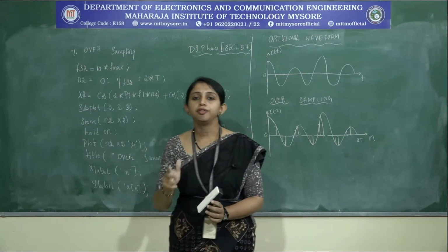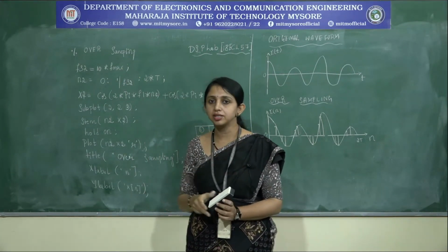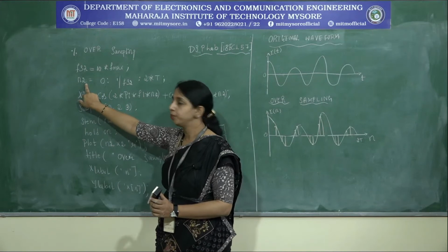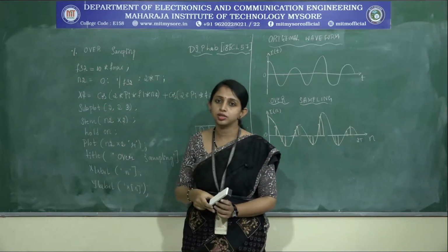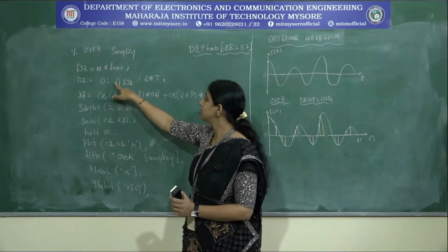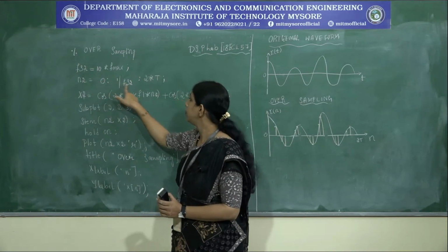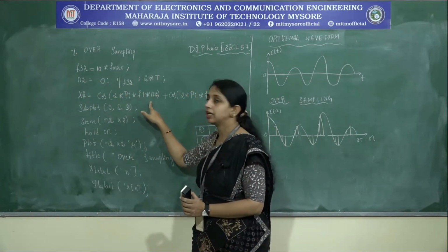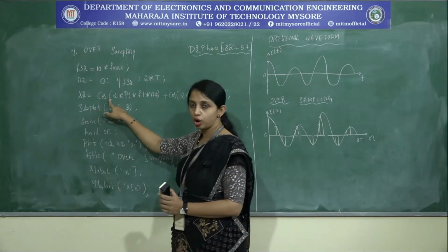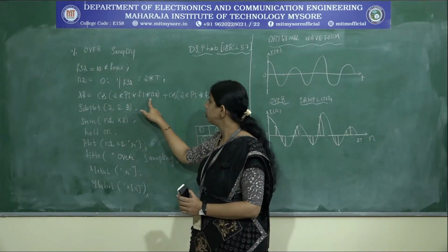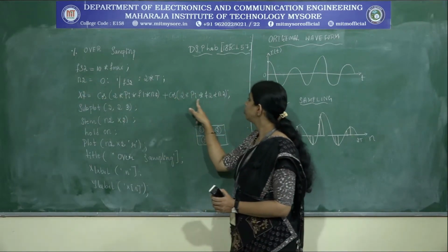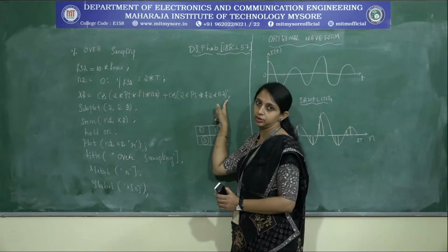Now you need to define an x-axis, that is a discretized value for this particular waveform. Hence write it as n2 equals, again the waveform has to start from 0, it has to end at 2t. And the intermediate value will be the reciprocal of the sampling frequency, 1 by fs2. Then go for the construction of the wave. So it is x2 is equal to cos 2 pi f1 into the considered discrete value n2 plus cos 2 pi into f2 into n2.